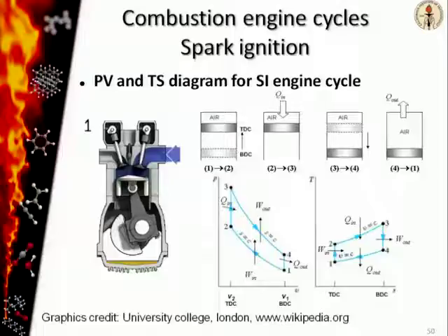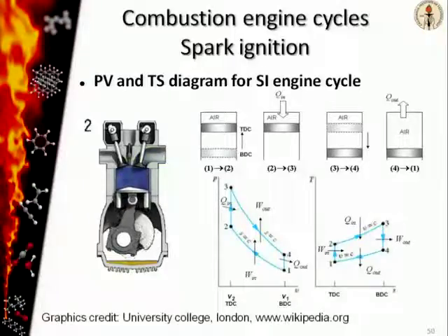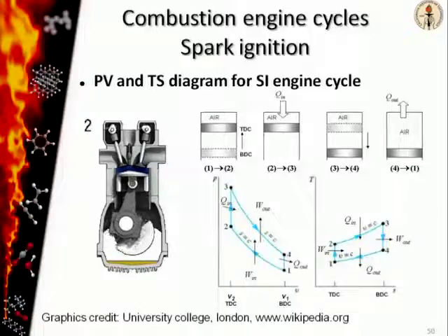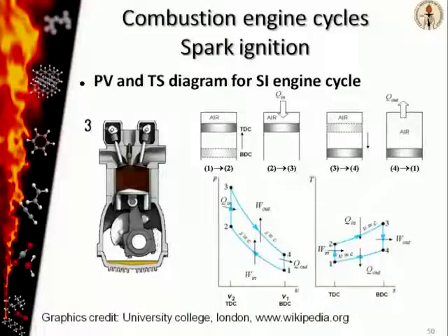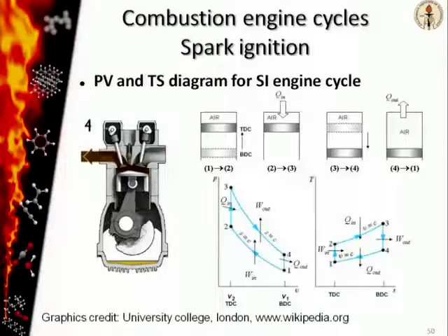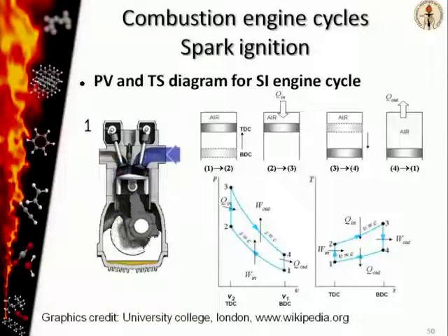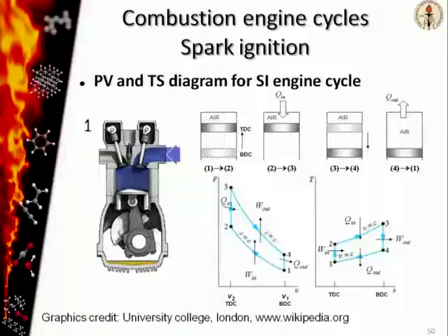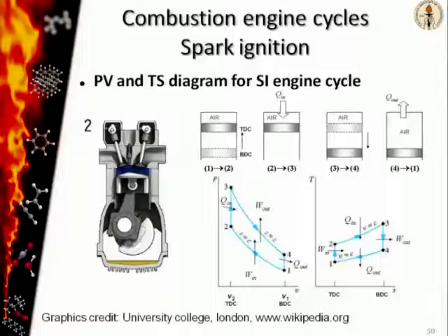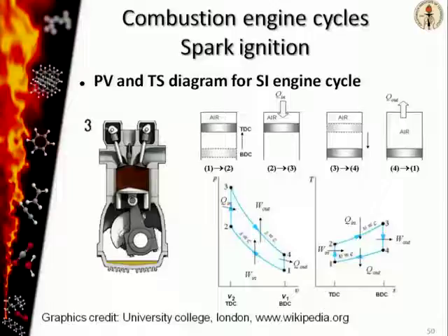So to briefly illustrate the working of the SI engine cycle, it must be from high school textbooks. You might have seen the operation of the SI engine cycle, but the figure here shows an animation of the cycle. The different positions of the piston inside the cylinder are illustrated here, and the graphs are the pressure-volume, or PV diagram, and the temperature-entropy, or TS diagram. These diagrams allow you to track the thermodynamic property of the mixture inside the cylinder during the course of the cycle.